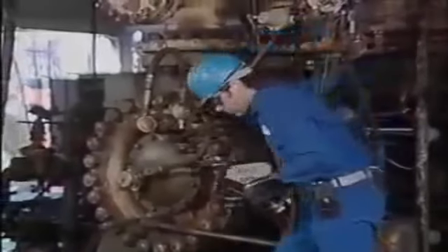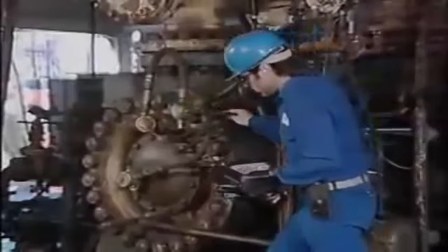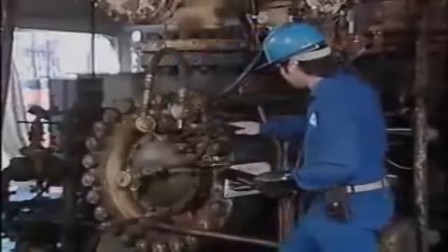Most centrifugal and axial compressors operate at very high speeds, usually several thousand revolutions per minute. So they must be started up and operated properly, or they can be severely damaged. A compressor startup consists of a series of steps. These include preparing the compressor for startup, warming up the compressor, and starting the gas flow to the compressor. The warm-up is continued as the compressor is brought up to operating speed. In our example, the compressor is used to compress a gas that is supplied from storage tanks.